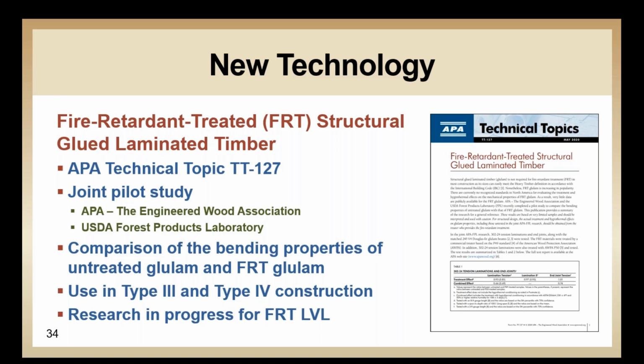Recently, APA published a technical note summarizing the results of this pilot test program examining the structural properties of FRT glulam. For structural design, the actual treatment and hygrothermal effect on the glulam properties need to be obtained from the treater who provides the fire-retarded treatment. Additional research on fire-retarded treatment for LVL is still ongoing.